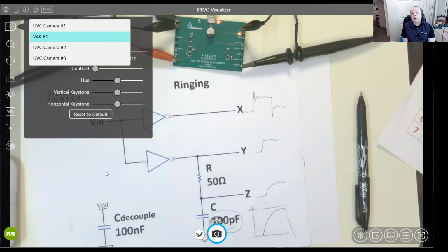Let's see now. Well, I2C is really a board level interface. We're getting about 6 months ahead of ourselves here. But I2C, of course, is a board level interface. It's not designed for going off board, really. If you want to go off board with I2C, then you really need to go via a differential driver.